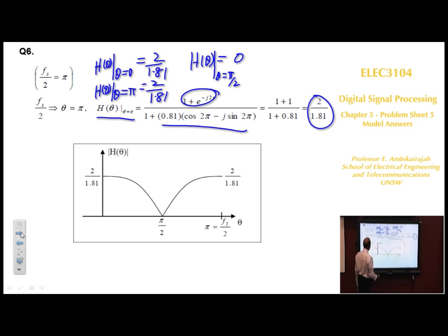So if you plot the maximum response, 1 there, 1 here, 1 there. So it's a perfect notch filter. It notches the value out. So notch means removing one frequency. That's why it's called a notch filter. So if you have got a 50 hertz and you want to remove it, you use a filter such that this becomes 50 hertz. So 50 hertz is no longer there in the signal. So it's a notch filter example. Not a design. I haven't done the design of a notch filter yet, but you should be able to plot, and looking at the maximum response, you should be able to tell what filter it is.